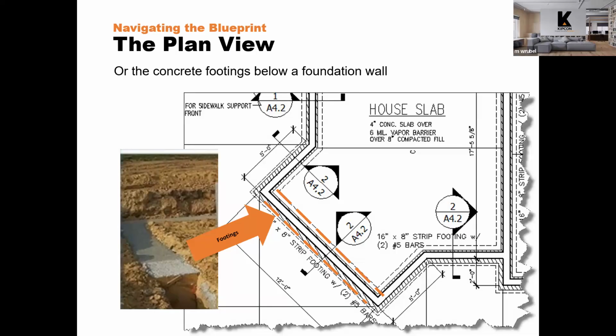If the footings are open, they would look at the plan set and see that the footings need to be so many feet wide, so many feet long, and they will measure that in the field just to make a comparison and ensure that the project is being constructed in conformance with the design plans.